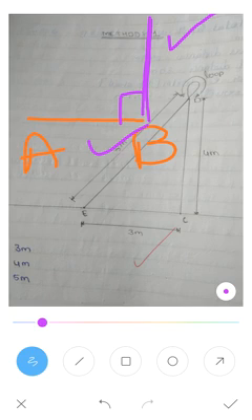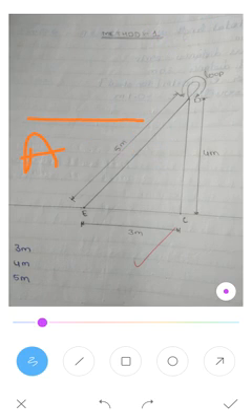So next, first I will explain the 3-4-5 method. The instruments used for erecting a perpendicular are a chain, tape, arrows, ranging rods, and cross staff. A perpendicular at a point on a given line may be set out by the following method, the 3-4-5 method.